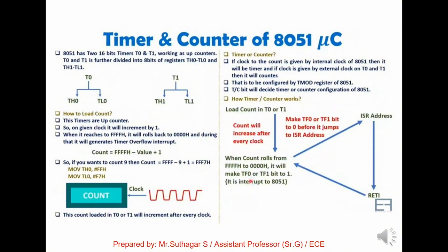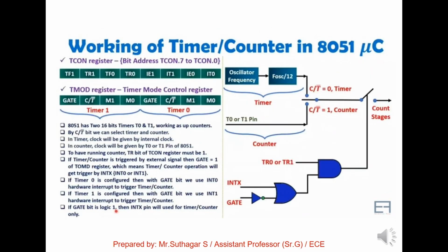Then it goes back and services the routine over here, and after completing the interrupt service routine, after executing this instruction RETI, it comes back to the main program. So this is the working of timer or counter in the 8051 microcontroller, and these two registers we have discussed already.